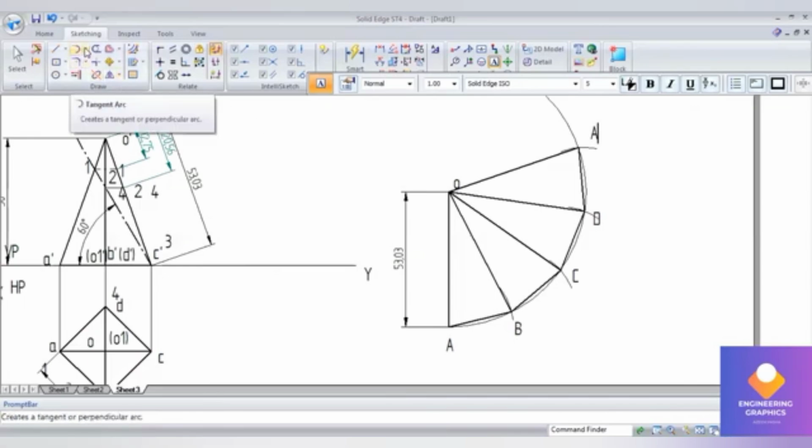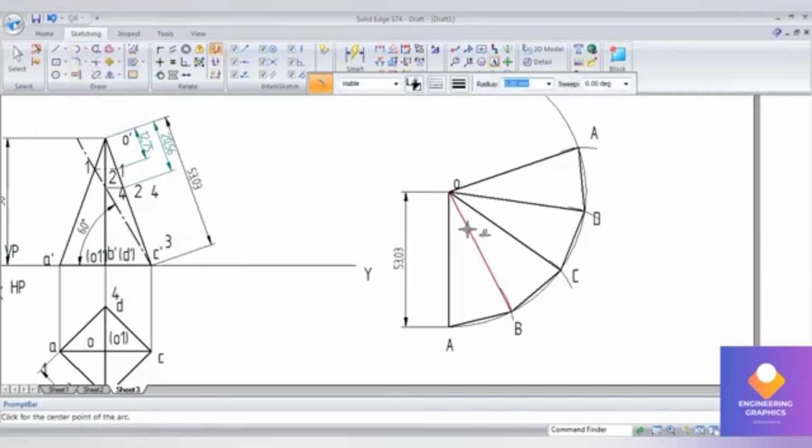Okay, now the upper part we have to show that section plane numbering. Okay, the one it is cutting at a distance of 12.75, enter, cut the arc. So you can cut this arc on OA. Give the radius correctly, 12.75 you have to give, and give enter and sweep it. Okay, 12.75, enter.